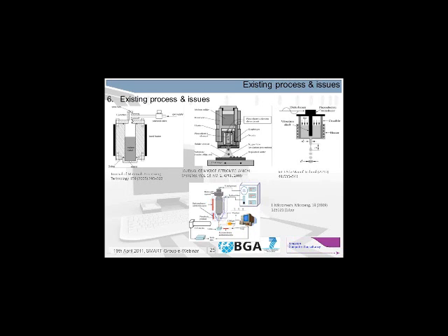The system itself was just governed by pressure, where the internal pressure within the molten solder tank was balanced against the surface tension that stops the solder ejecting, and the process control was solely by the pressure of the nitrogen within the tank.